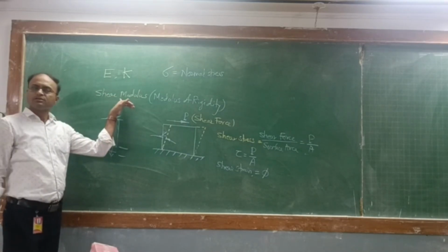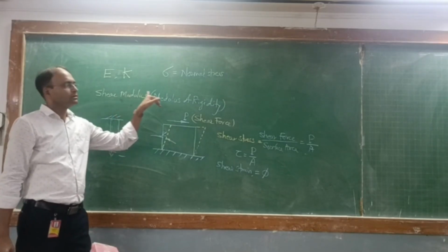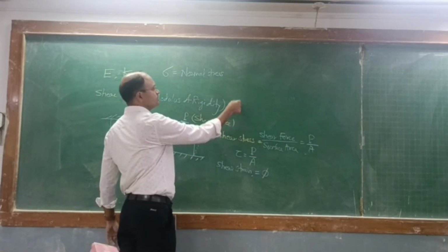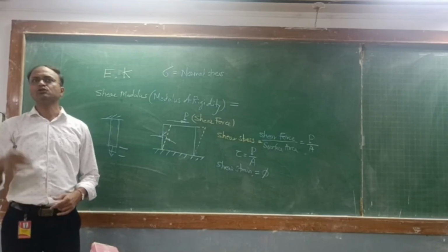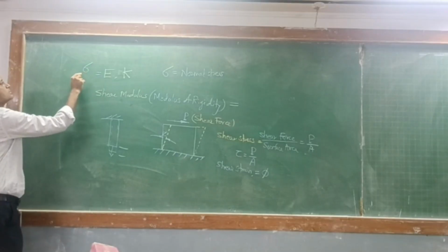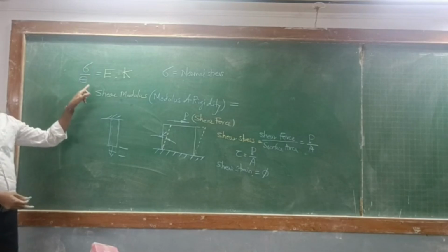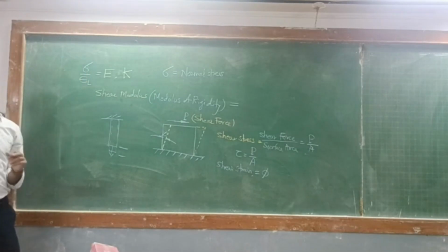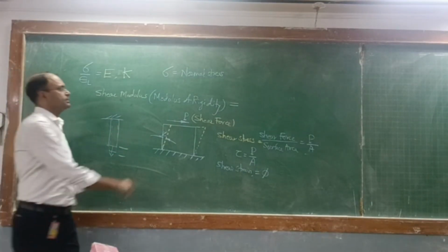Shear modulus. Next line. Shear modulus or modulus of rigidity is equal to... Young's modulus क्या है? Ratio of stress upon strain, or more specifically normal stress upon longitudinal strain. This is normal stress. This is longitudinal strain. Correct? वैसे shear strain, shear stress upon shear strain.